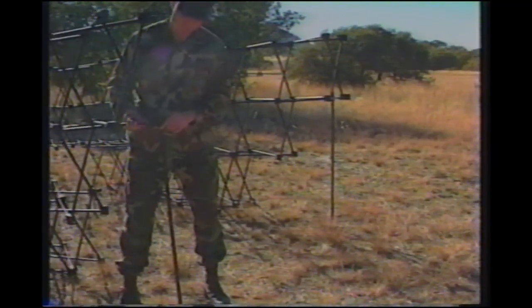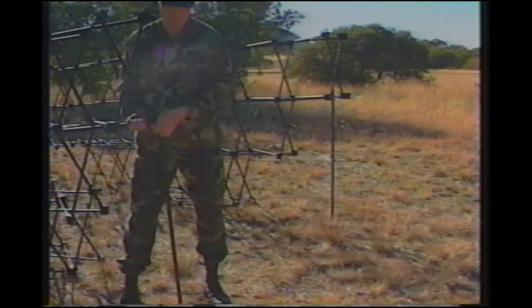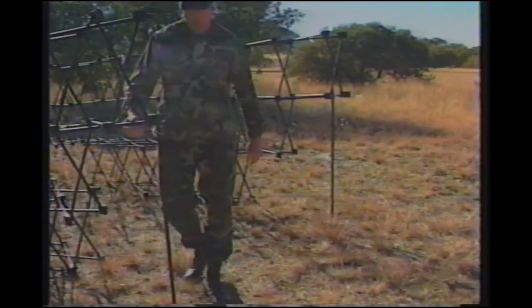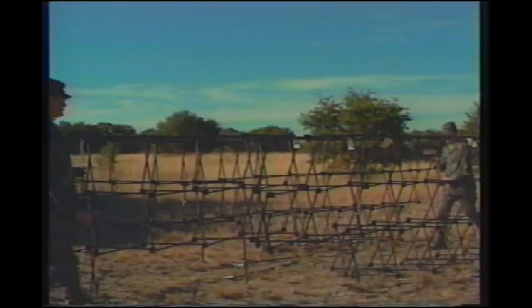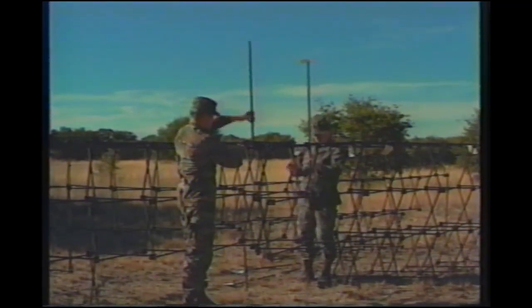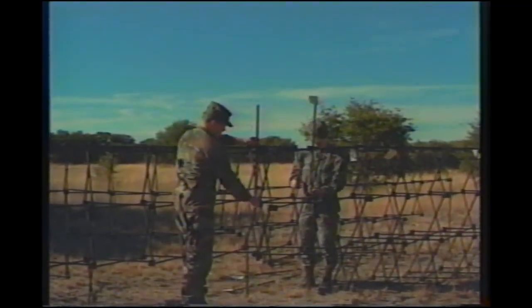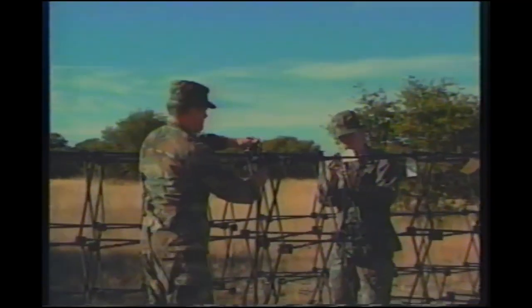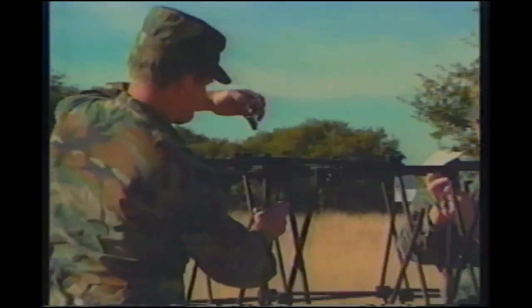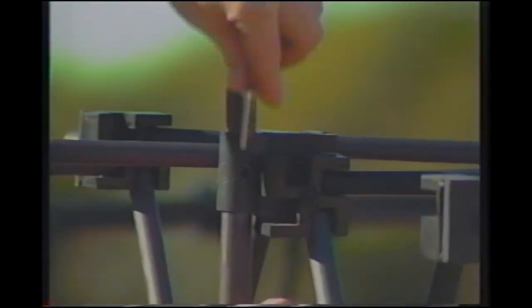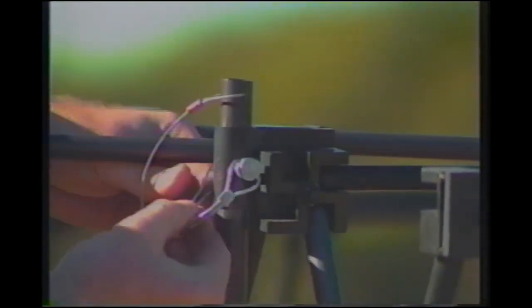Slide the safety snap pins through the support legs below the frame collars. Secure with the attached spring wires. Now, connect the side frames to the front frames by inserting the frame connecting tubes through the front and side frame collars. Secure with safety snap pins through the holes in the collars and the connecting tubes.